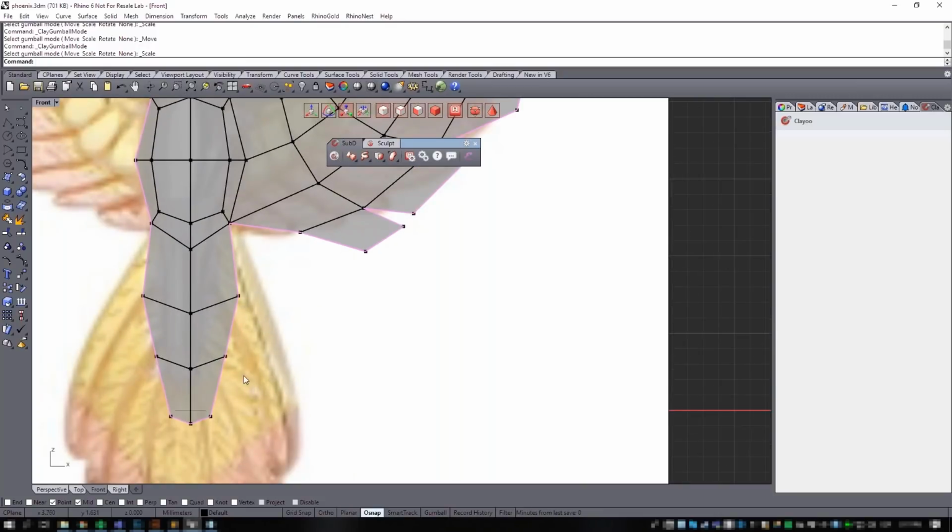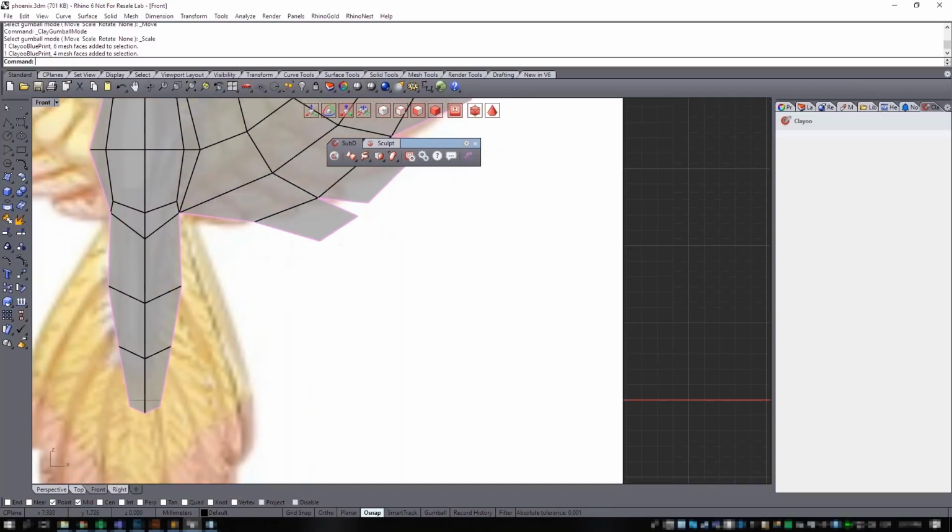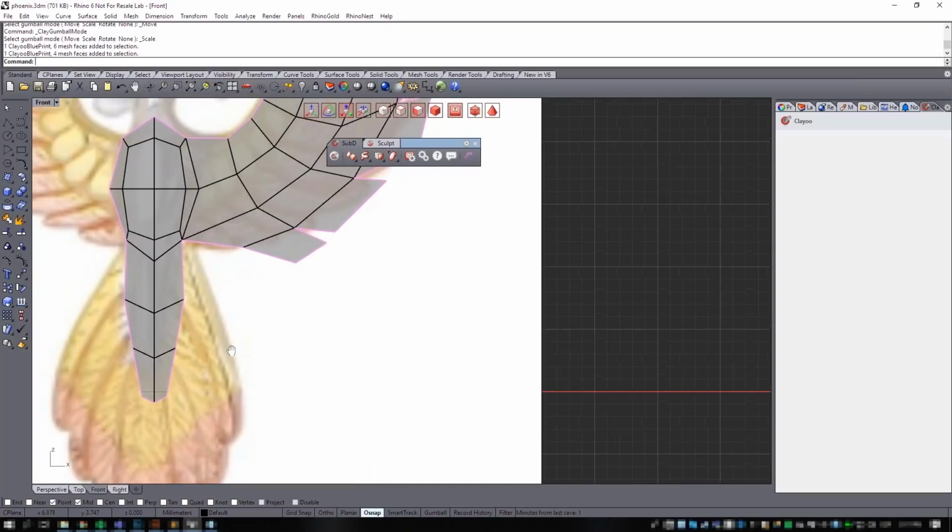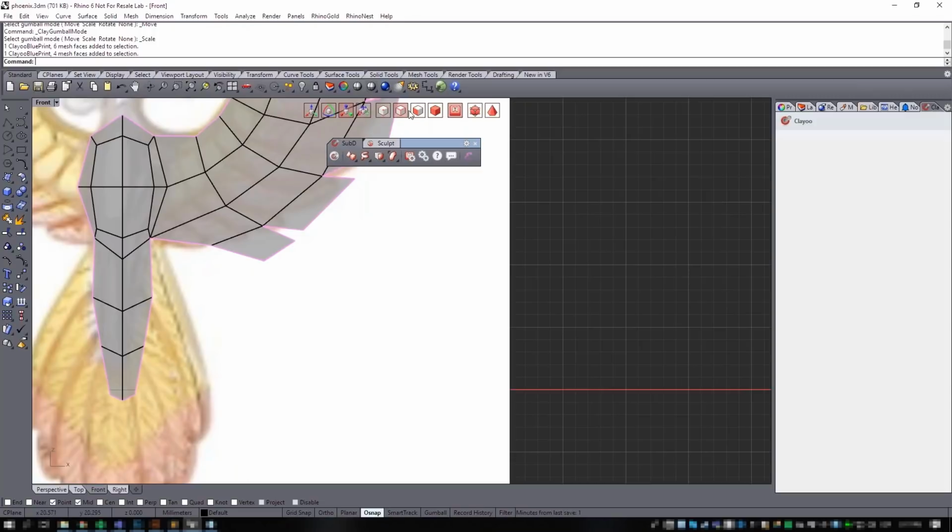Okay, from here, maybe we can just slightly refine that, but like this, it's looking pretty cool. Maybe we can select all these faces in here and reduce that a little bit. Okay, there we go. So from here, we're gonna start creating the different feathers for the tail. So I will select in the edges, select this edge, W, holding Alt, and drag it a little bit.